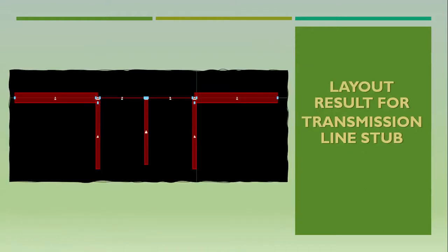Okay, this is the layout implemented from the ADS circuit, and we get this layout. This layout is according to the Z0 and this is the RL. This is the MLOC, 65, 70 and 65, and this is MLIN. So this is the layout for the transmission line.